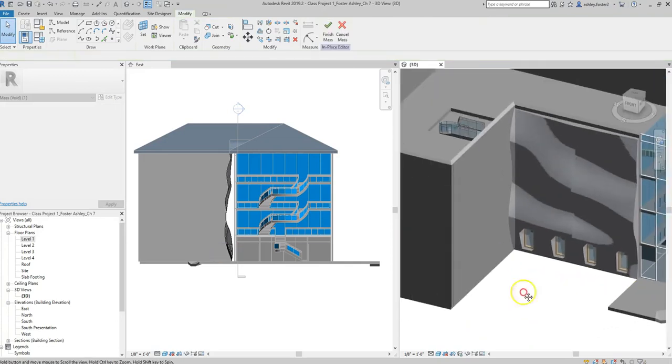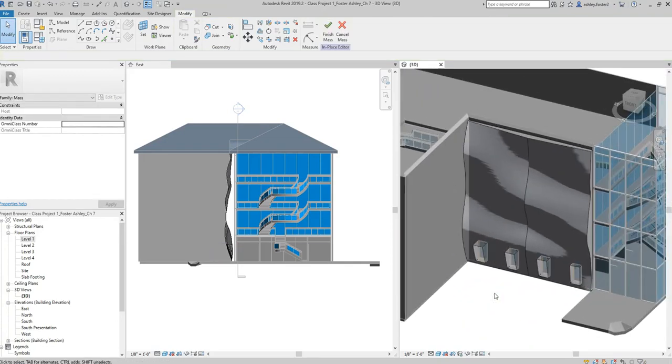There we go. You can also do a similar type of facade to what we did with the bench, where we created one extrusion from the very bottom to the very top, and then you can do a linear array and add a bunch of voids in order to make it look like slats of wood.